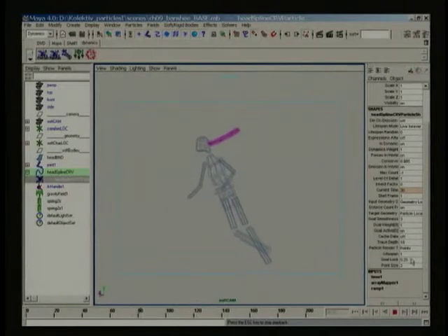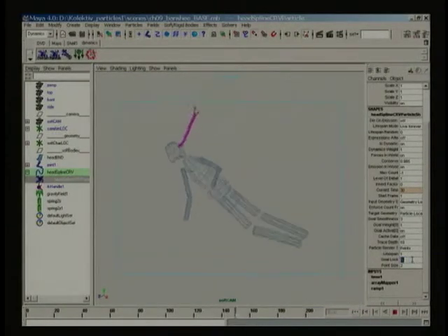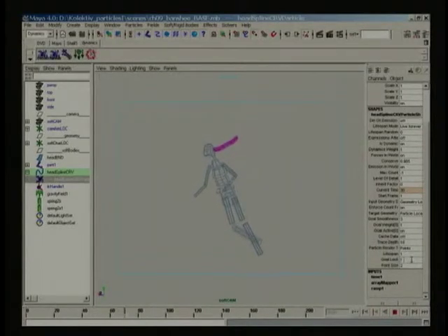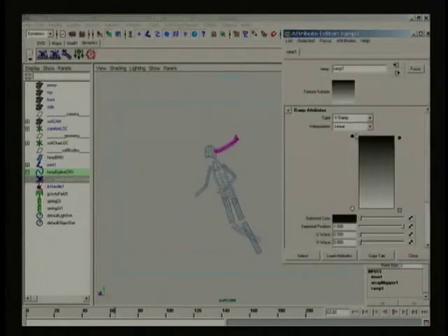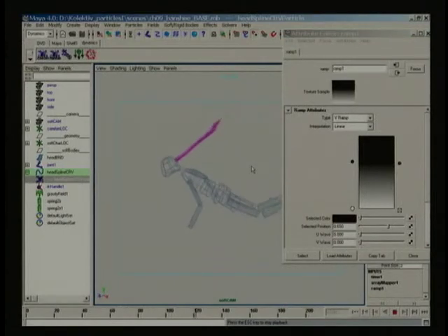I'll set goal lock to a value of 0.25 to stiffen up the softbody. Another advantage of goal lock lies in its ability to be keyframed. Setting your goal lock to 1, you are able to move your character to a different position, then keyframe it down to a lower number a few frames later.